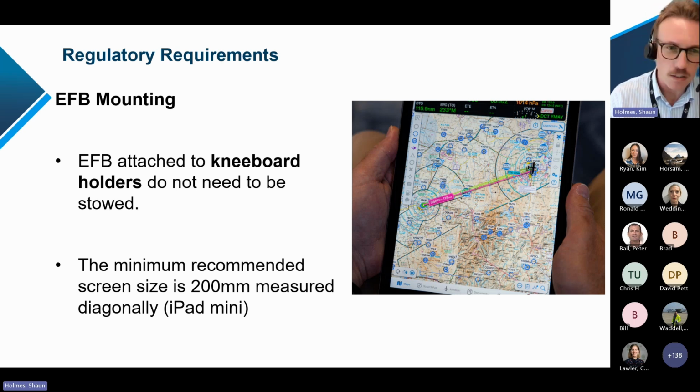Why? It's a different mounting mechanism rather than, say, suction or clamping, and you're also going to have an increased awareness of the security of the device because it's attached to your person. As for who can provide an airworthiness approval, the best thing to do would be to speak to your local maintenance organisation. They would be looking to obtain an approval for you under subpart 21M of the Civil Aviation Safety Regulations, which deals with modifications of aircraft.